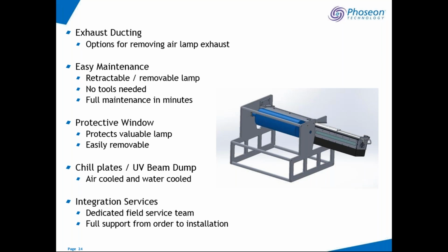So it's important to continue that maintenance and to scrape those windows as necessary to have sufficient life for that lamp. We do have protective windows as well, often found in environments that are incredibly dirty. Where we place these lamps, you can quickly pull that protective window off and put a new one on while you're going to clean the older one.